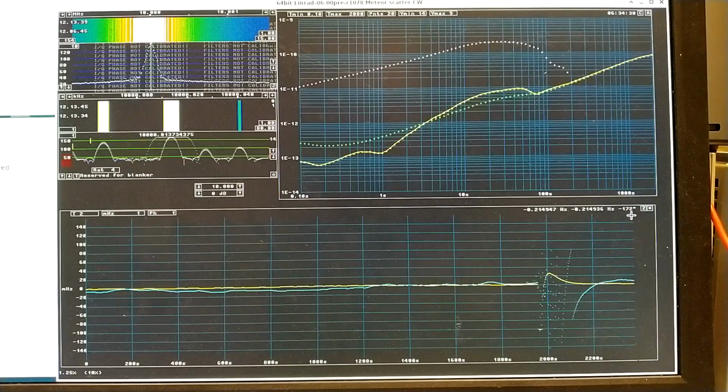At this moment it is minus 172 degrees. And I have changed the scale so it comes near 0. What happens here is that the phase turns 360 degrees. 1, 2, 3, 4, well, maybe 10 times or so. That is because locking is done on a fraction of the frequency. I have a divide by 16. Otherwise, it would have lost locking for this big frequency shift.